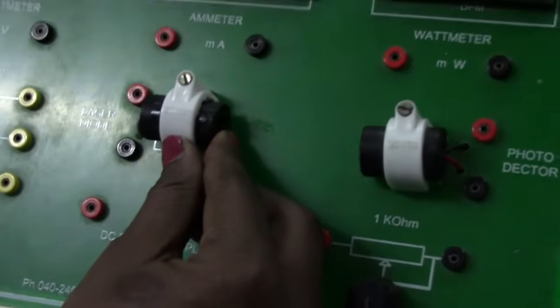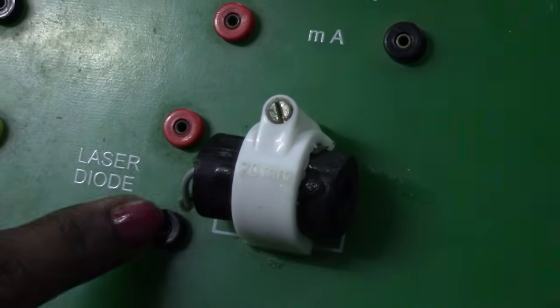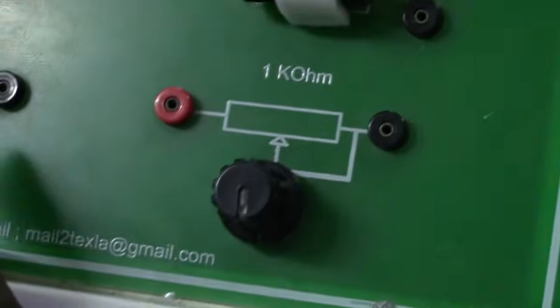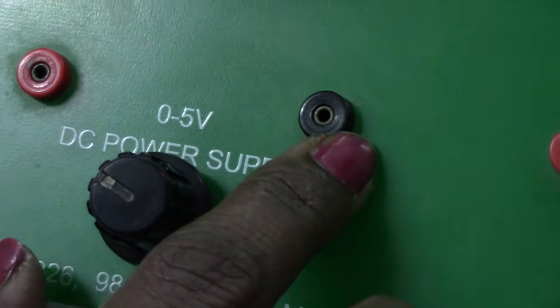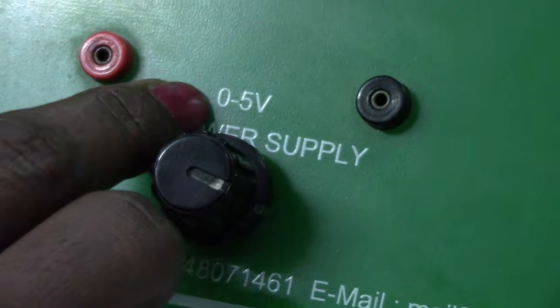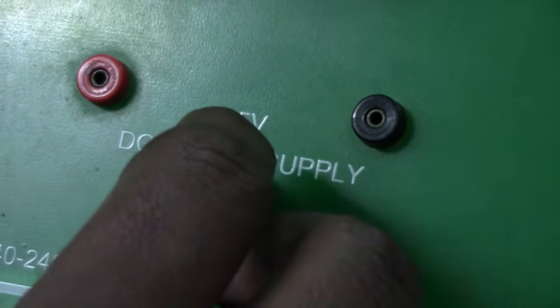Coming to another device, our laser diode. This is the laser diode whose terminals are here. Red indicates positive, black indicates negative. And we have a 0 to 5 volts variable DC power supply. These are the battery terminals. Red is the positive terminal, black is the negative terminal, and it is a variable power supply. That is the reason the knob is connected here. Between 0 and 5 volts, you can rotate this knob to whichever voltage value you require.